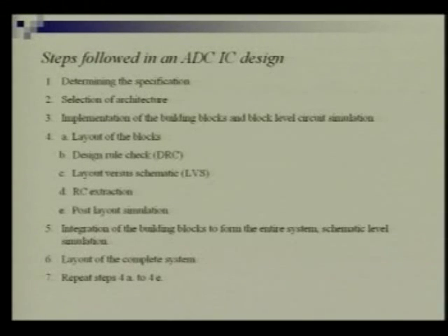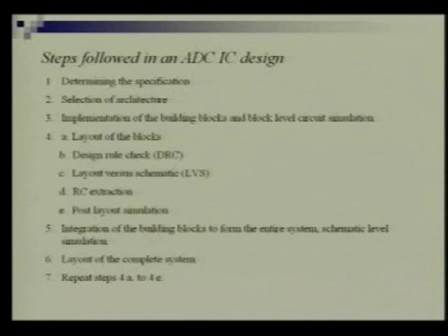Then after design rule, according to the design rule, you have done the layout. But still there can be something wrong. So you are to do this layout LVS, which is layout versus schematic. You have designed a circuit, transistor circuit. After that, you have translated it in its layout form. But when you have translated it in its layout form, there you may do something wrong. So LVS takes care of that, layout versus schematic, that what schematic you have done and what layout you have done, whether it is corresponding to each other, that verification is done in the LVS step.